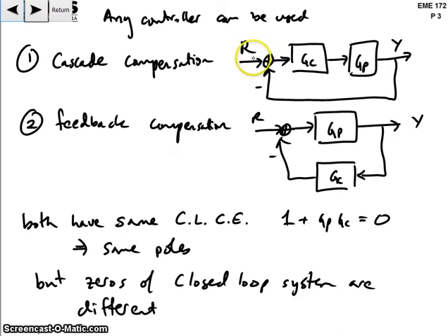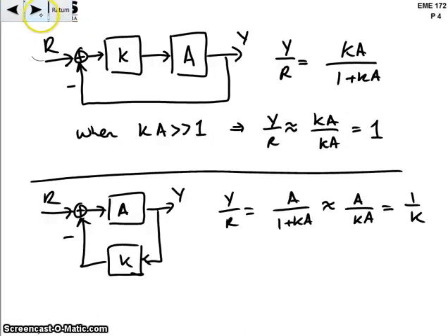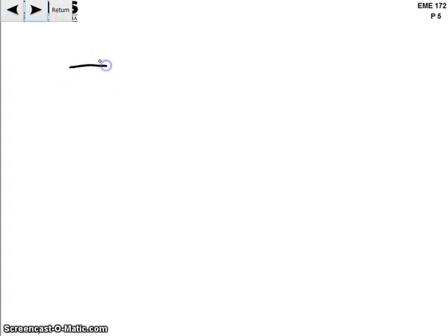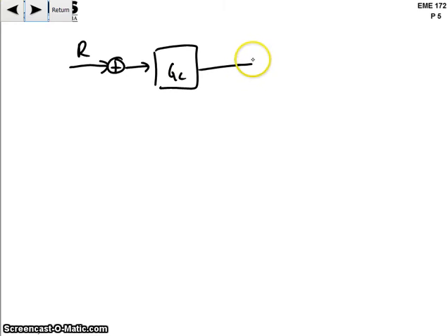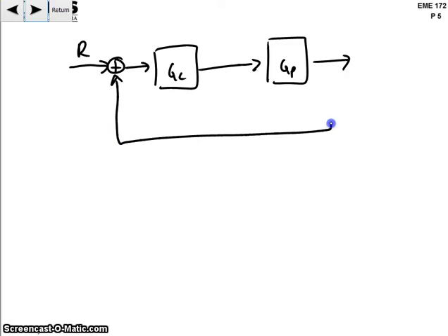So what we can do is we can actually inject the reference here, and we can also inject it. I'll draw a little picture here. So here's the reference signal. Here's the controller. Here's the plant, right? Remember, we know the reference signal. We're generating this input to the plant. This is the output of the controller, U, here. And so what we want to do is avoid the time delay it will take for the signal to propagate from the error to U, so whatever the time delay is through this controller.